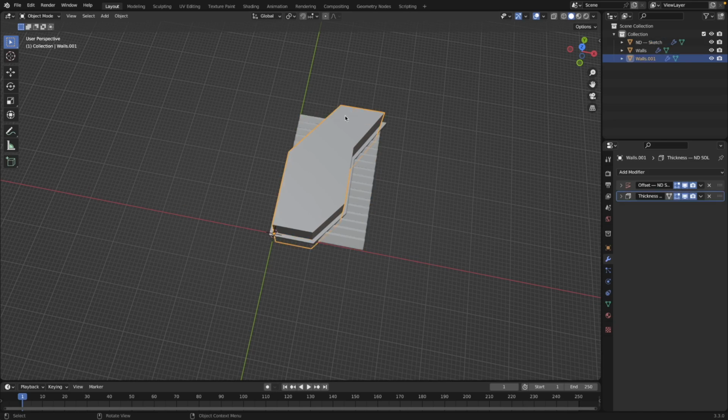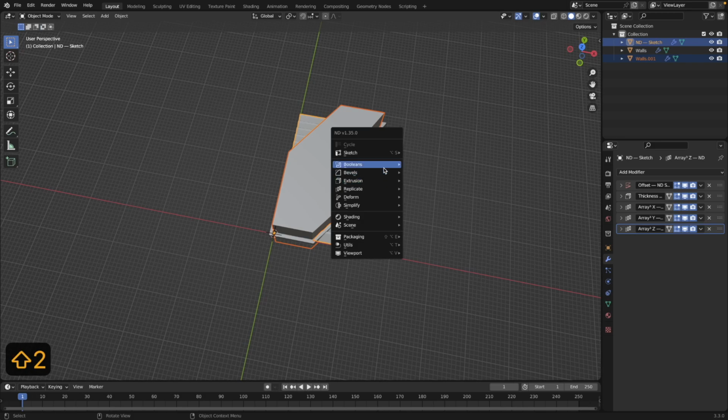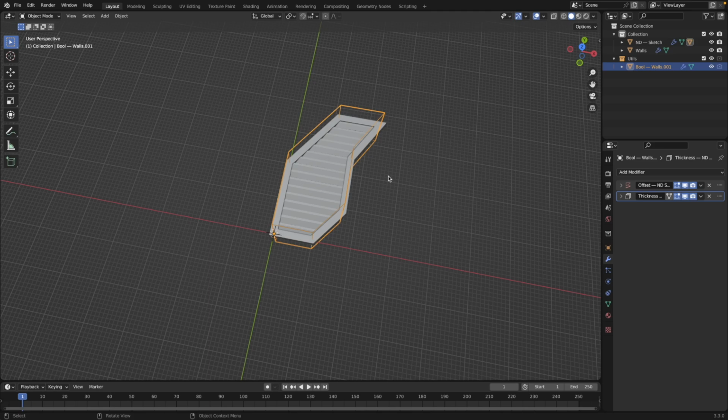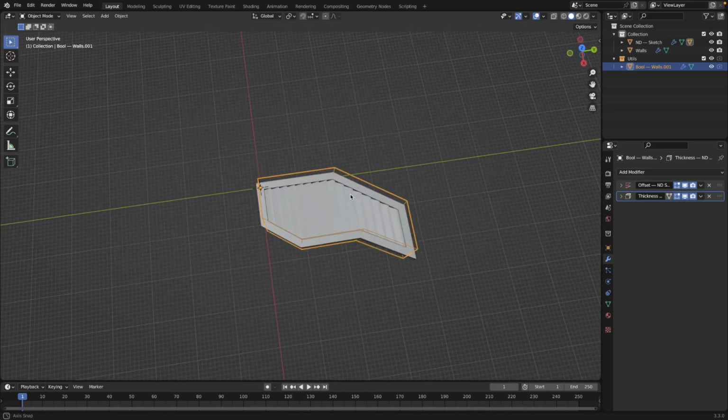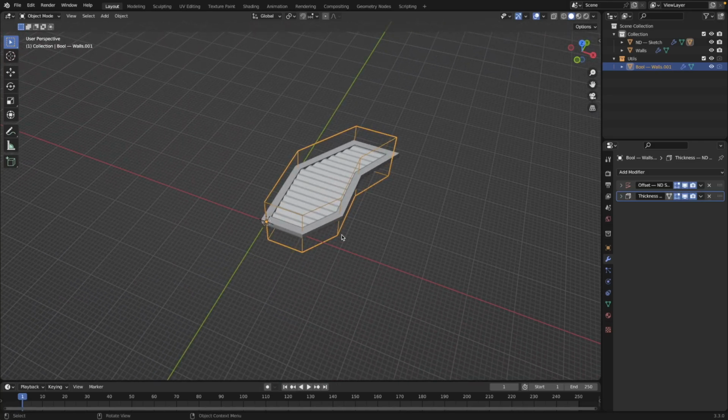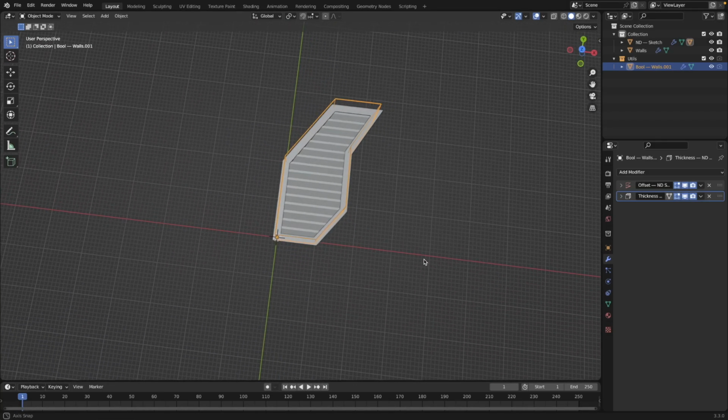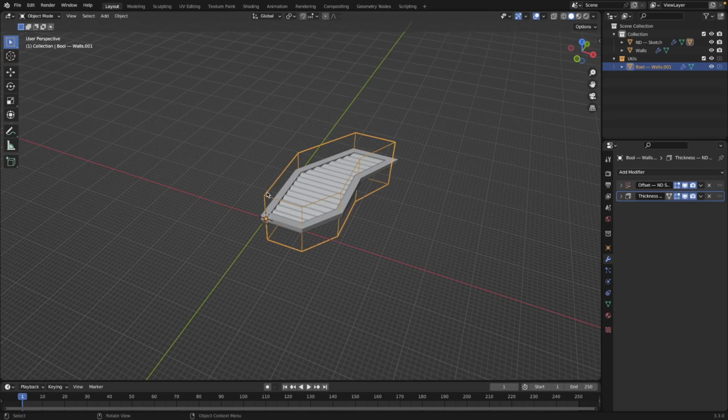You want to select the object that you're using to cut away first. So that's this big chunky object we created. Then you hold down Shift and select your second object, the one that's going to be cut. And with both of those selected, then we hit Shift F2 to go into the ND menu, choose Booleans and choose intersection. And now only the part of those fins where they intersect with that outer shape that we created are still visible. So that's perfect.